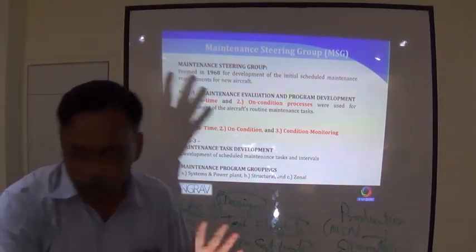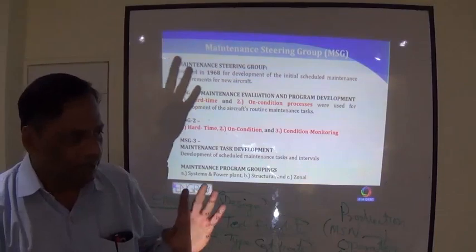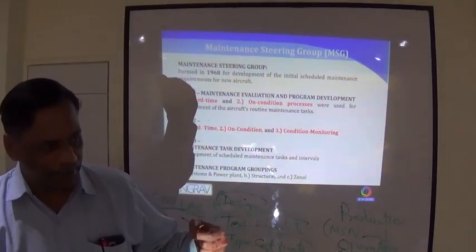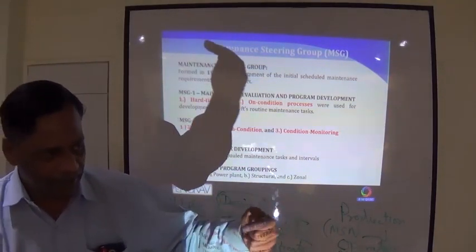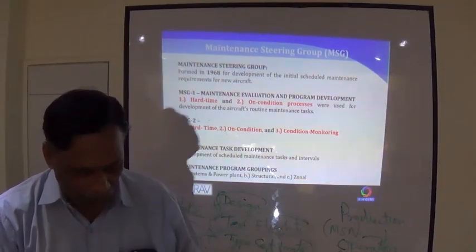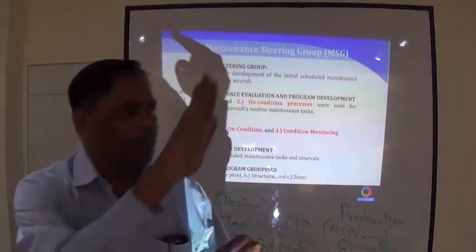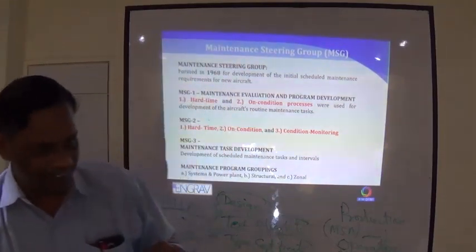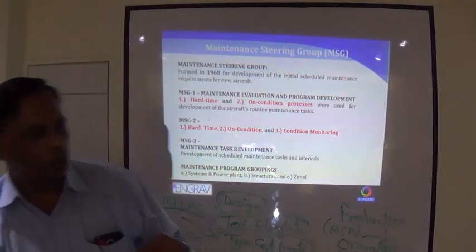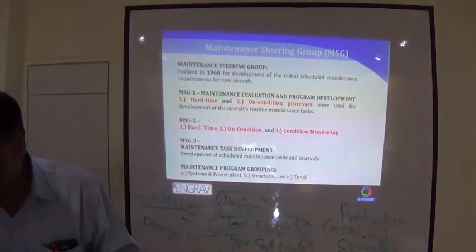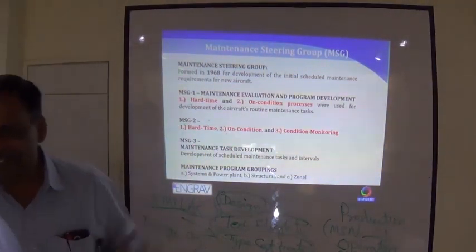Now when you make it too automated, these sensor inputs become critical. The computer sees the malfunctioning angle of attack indicator as the aircraft suddenly climbing, so it gives the correction to the autopilot to dive. This is what happened in that crash.